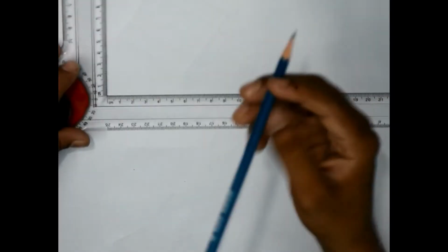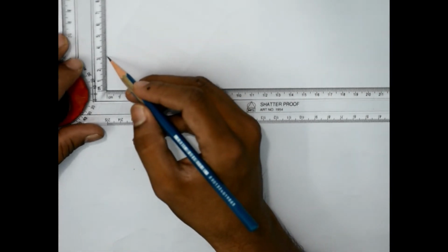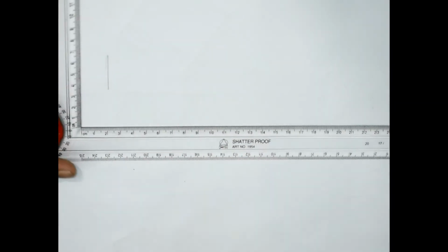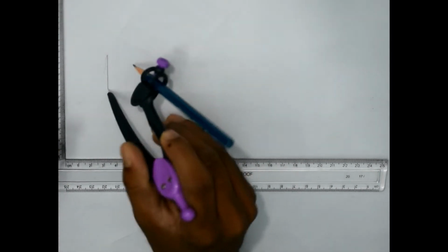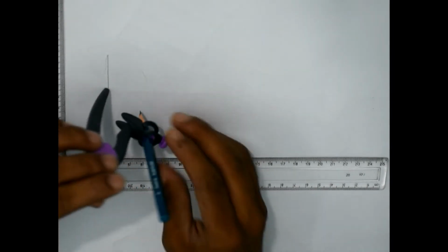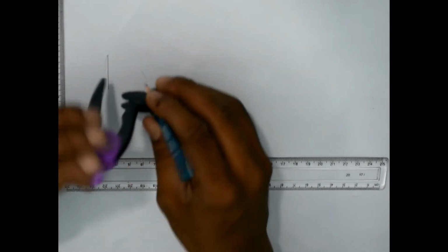As it is inclined to the vertical plane, first we will assume that it is resting on the vertical plane itself. As we have already seen, when it is resting on the vertical plane, there will be a hexagon in the front view, something similar to this. And I am drawing this with the 2H pencil. The reason being, this is just our assumption. This is not part of the question solution.